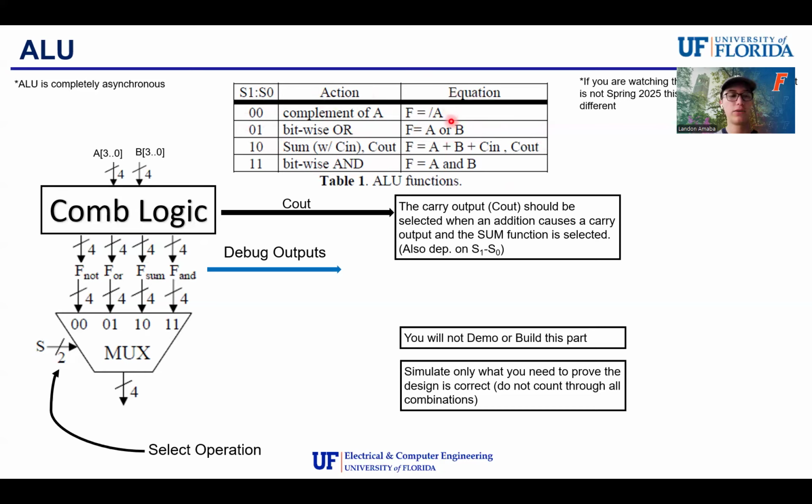So again, this ALU is going to be completely asynchronous. So immediately when you change these values of S1 and S0, it'll take into account that change and then it'll automatically populate the output of the mux.